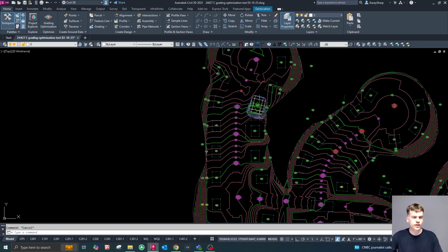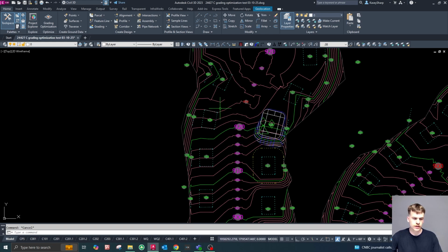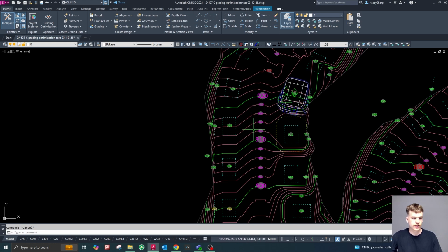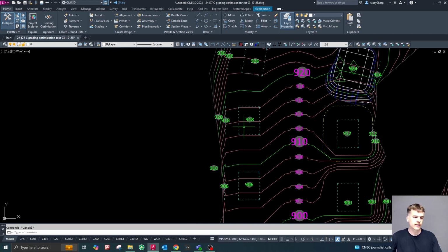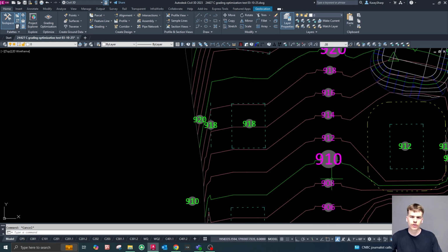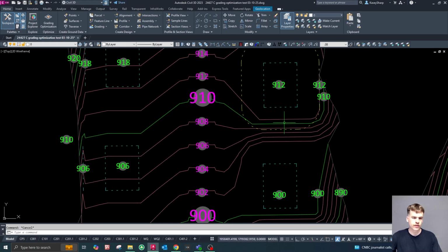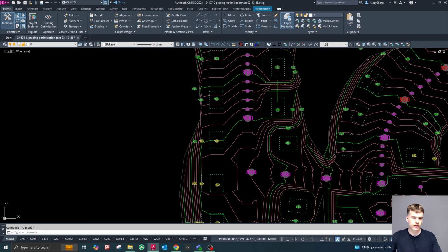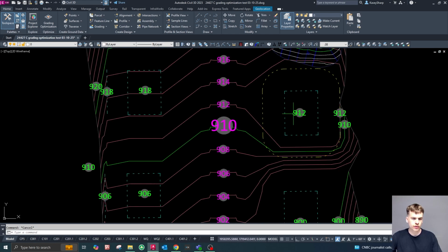So as you can see here, we have this large-scale residential project with a bunch of different homes on different lots. One of the issues that I have with the surface that was made from the corridor is that the lots themselves have a cross slope that matches the road. What we need is contours to be stretched apart and pulled together in between each house that's at a different elevation, like the right side of the road here, such that the building pads for the houses themselves are actually flat and you can build a house on them.